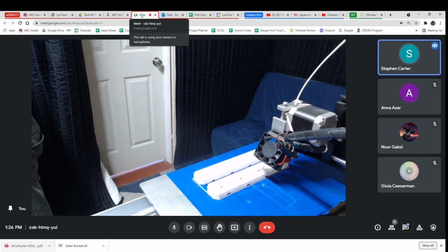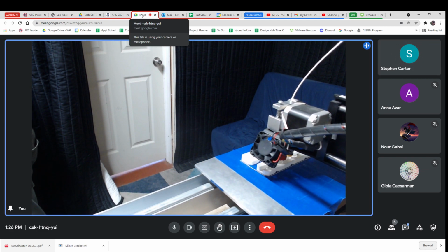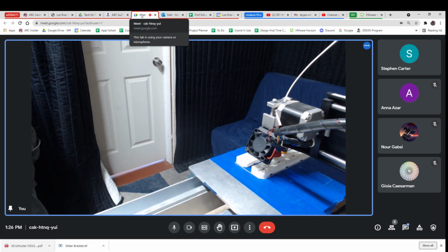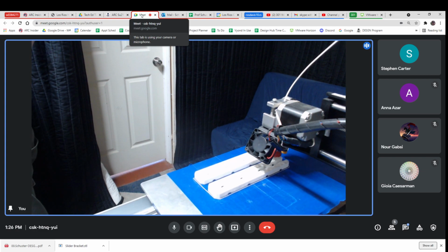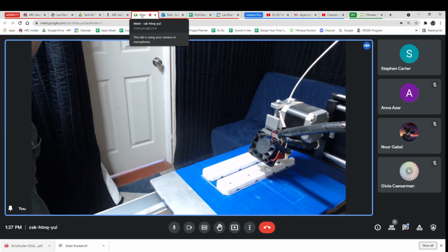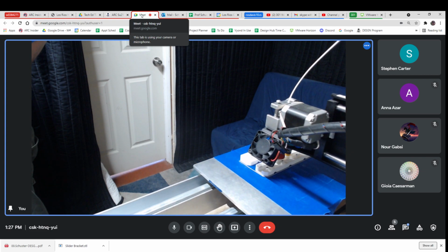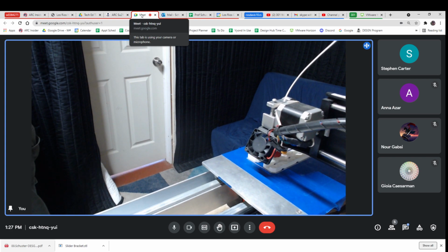But yeah, I think I do. I don't know yet. Yeah. Do you have a glass bed or do you have? Yeah, it's a glass bed. Yeah, you will not need anything if you get your temperatures right. You will absolutely not need anything. At the most, probably some hairspray. And then alcohol the hairspray off when you're done.